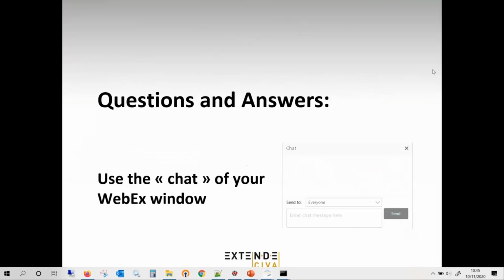So I have a first question from Mastan Papanabuana. When we are using sectoral scanning at 30 to 70 degrees, how to combine all beams together in one figure? So if you want to do beam mapping from 30 to 70 degrees, I guess, you know that already within CIVA you can accumulate all the fields. If you want to do the same with CIVA Script, well, it means you need to extract the beam maps for each angle.